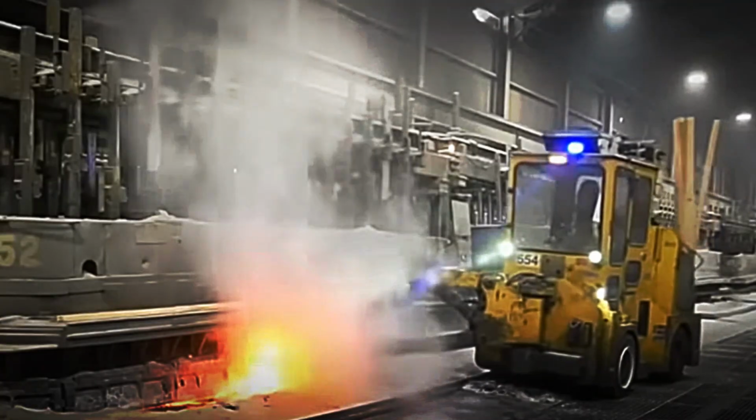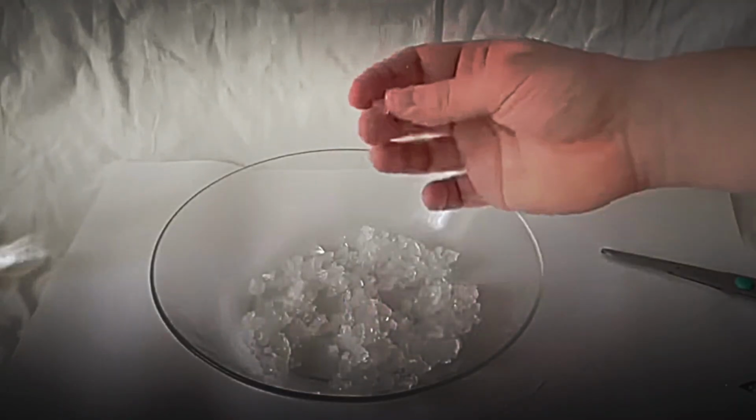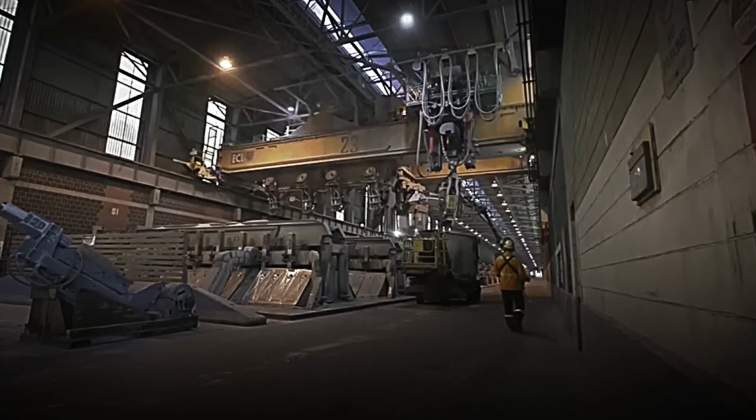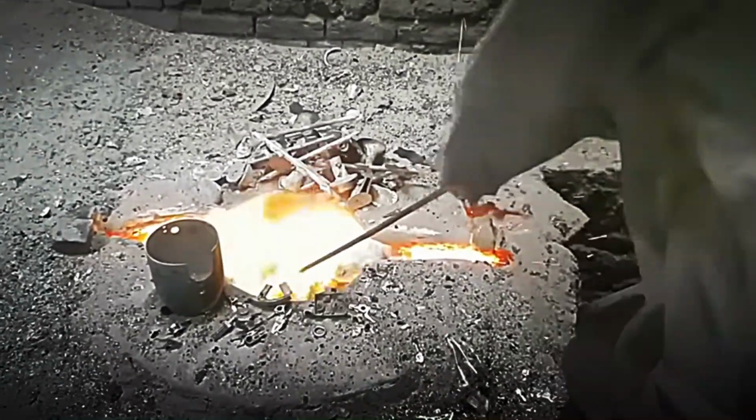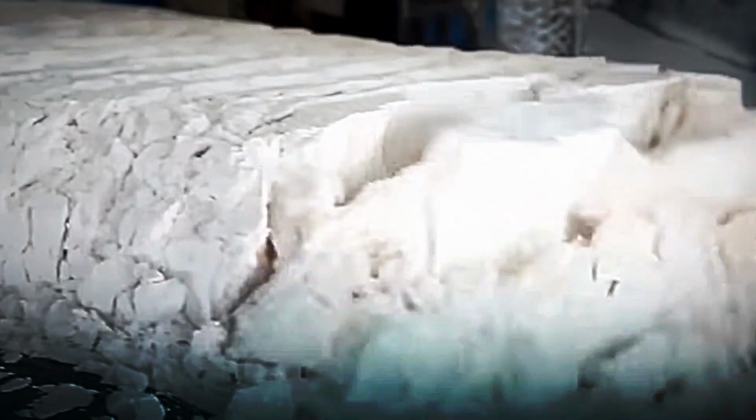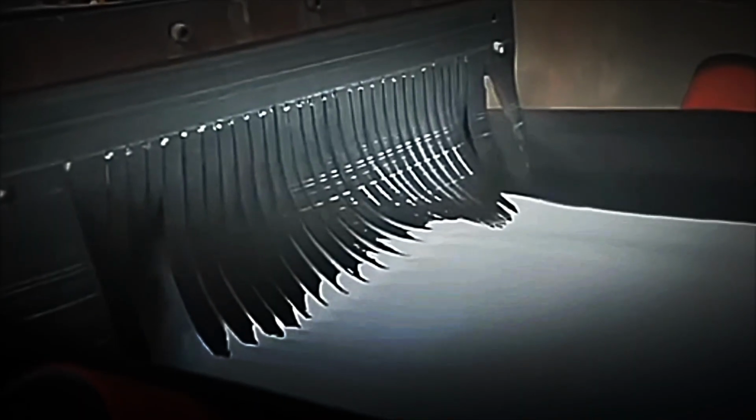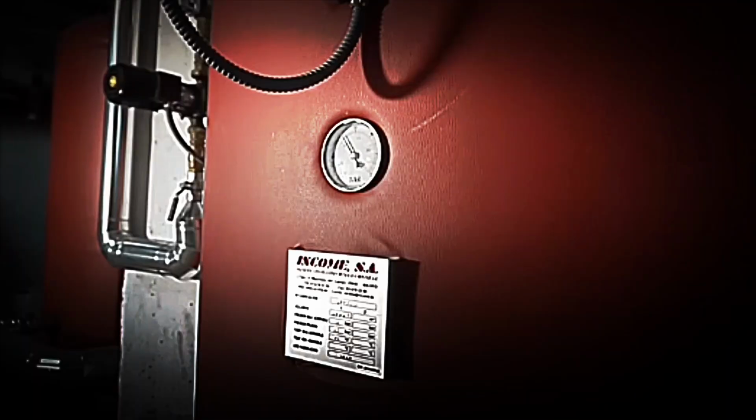This increase in temperature causes the thermal decomposition of the compound. The water contained in the crystals evaporates, and at the same time, impurities that could affect the quality of the final product are eliminated. The result of this process is a very fine white powder known as alumina, aluminum oxide, Al2O3. Although at first glance it may resemble flour due to its light texture and uniform color, it is actually a material with very different properties. Alumina is extremely heat resistant and constitutes the most important intermediate point in the entire aluminum production chain.